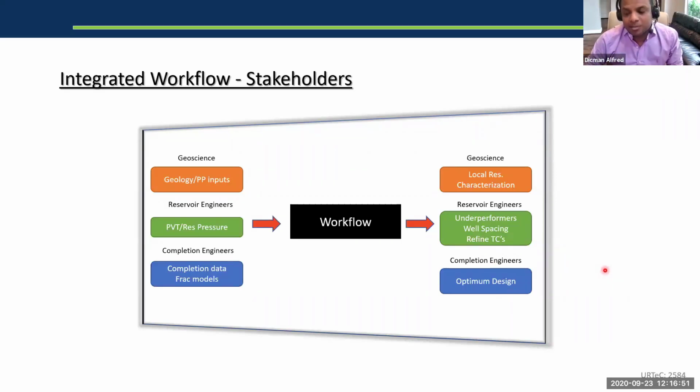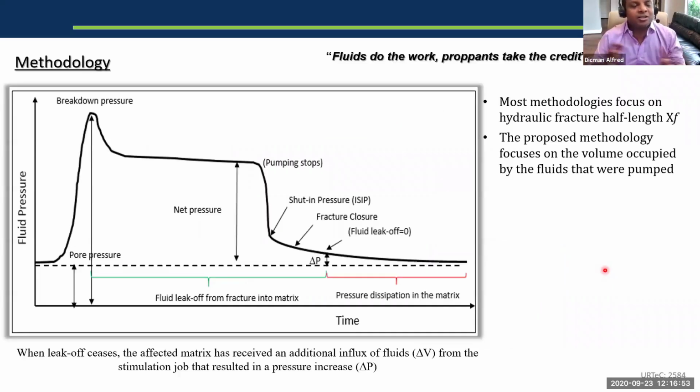Okay, so let's move on. So what's the methodology? If you look at the top there, I wouldn't want to name this wise guy, but he said, fluids do the work, proppants take the credit. It's actually true, because think of this. When you frack a well, you send the fluids first to frack it, and then you send the proppants. All that the proppants are doing is sitting inside those stimulated fractures and getting pressed.